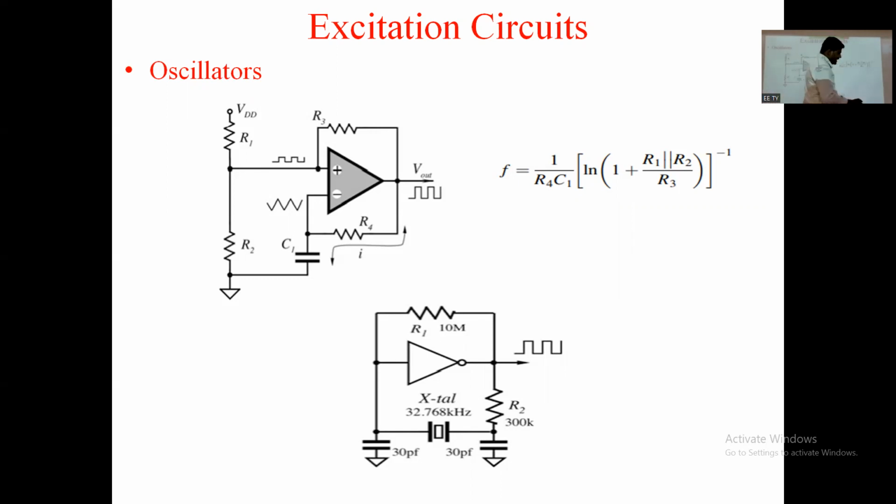So this is related to the excitation circuit. This excitation circuit is used to excite the active type of sensor, right? To enable that sensor operation, we are using an excitation circuit, and these are the different types of excitation circuit, which depend upon the type of sensor or operation of that sensor, like some RTD or thermistor type sensor, some humidity type sensor or pressure type sensor.